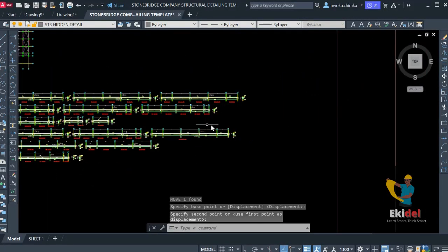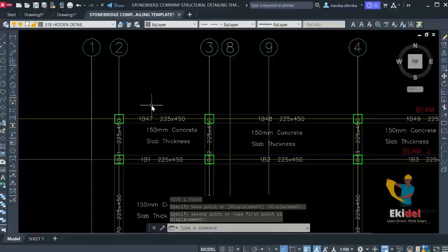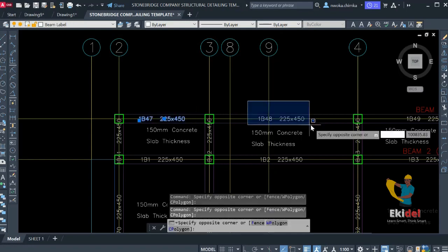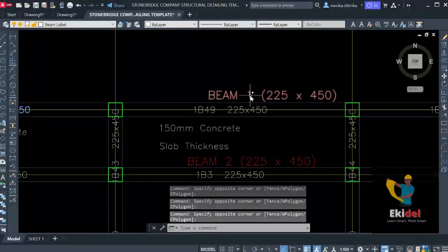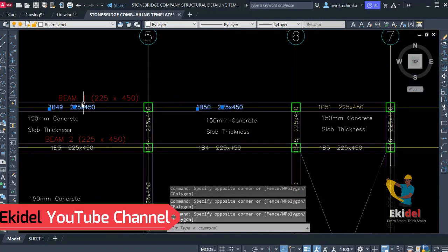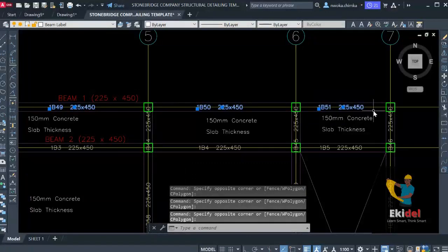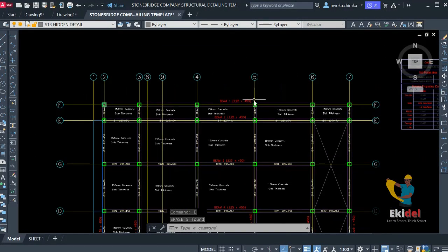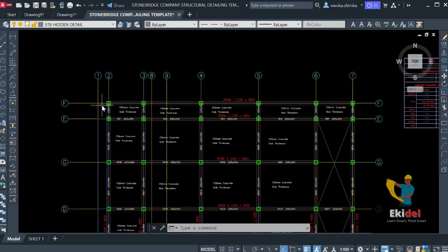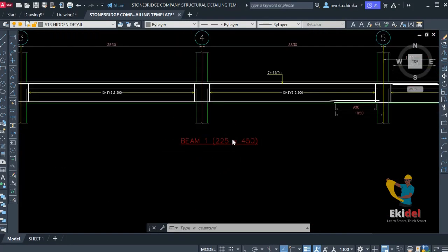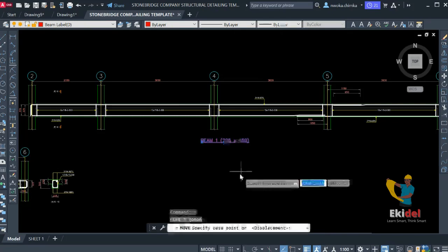So first thing I'll do, we also remove this because we have now numbered this beam perfectly. So we remove this beam detail, this beam name, and leave just this one because this now overrides all other beam names that are on this beam. So we now remove this and delete. So that's the beauty. If someone reads your drawing, you can see that this beam 1 is simply saying that all throughout this beam is beam 1. So the person goes to your detail and locates beam 1, which you just see here, and this is beam 1. Let me just move this upward a bit.